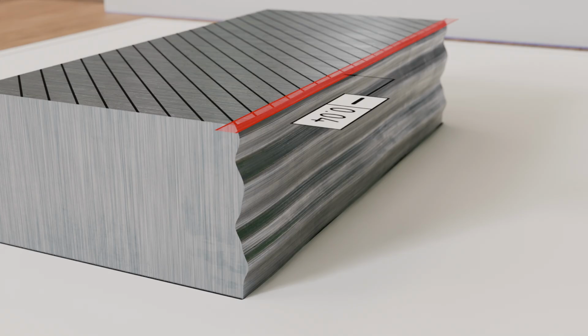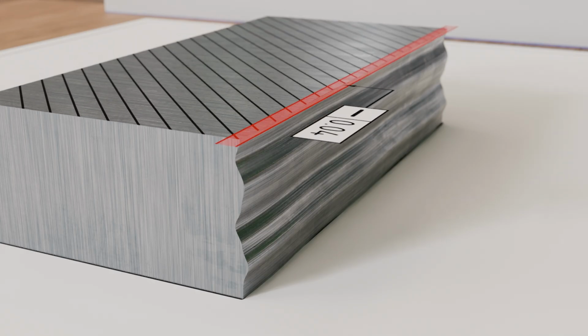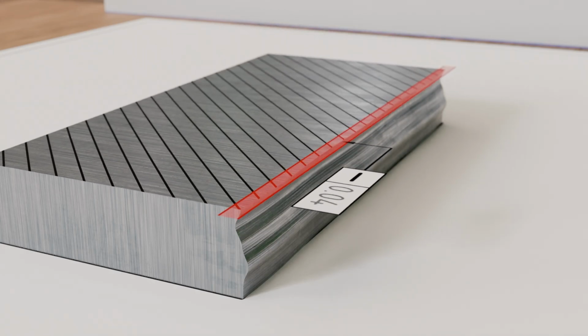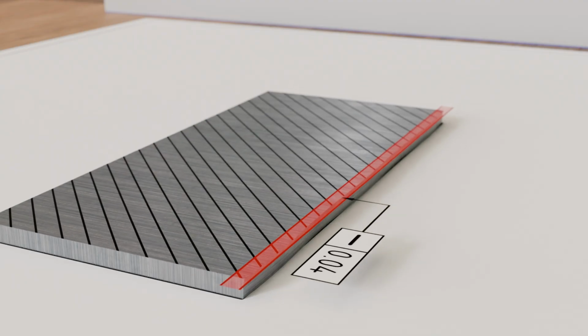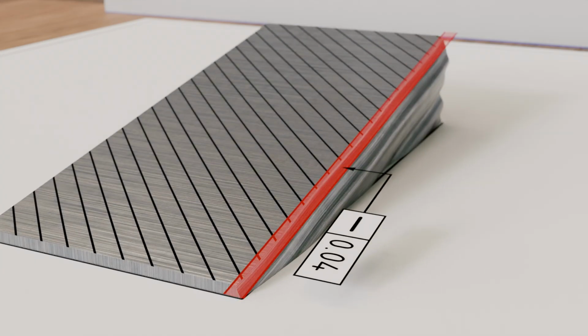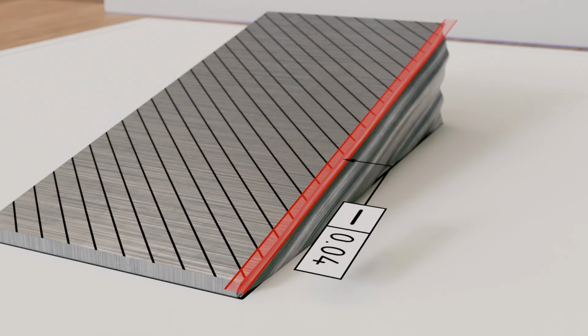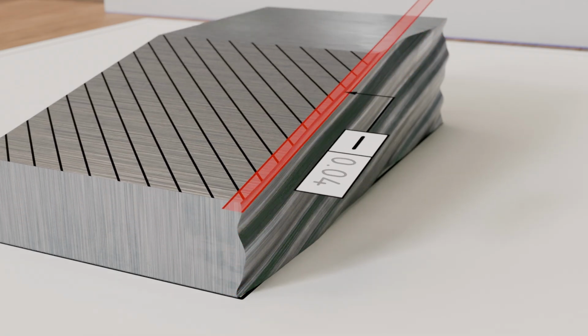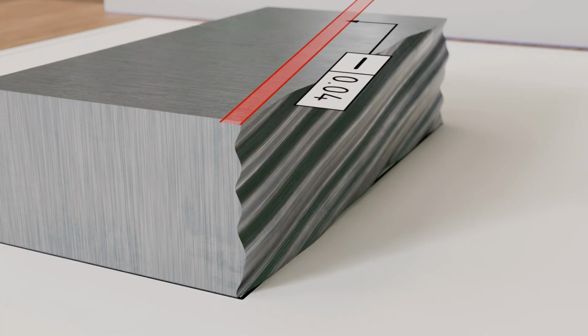This means that straightness only needs to be maintained in one direction. Perpendicular to that, the surface can theoretically have any waviness, as is the case in our example. But the question arises, who determines the direction in which straightness must be maintained, and in which it may be wavy? Here, we have implicitly assumed that straightness is required in a cross-sectional plane parallel to the drawing plane. However, the conceptual cross-sectional plane used to define straightness could also be oriented at a different angle relative to the drawing plane. Without additional specification, the supplier could essentially choose any direction for the straightness requirement.